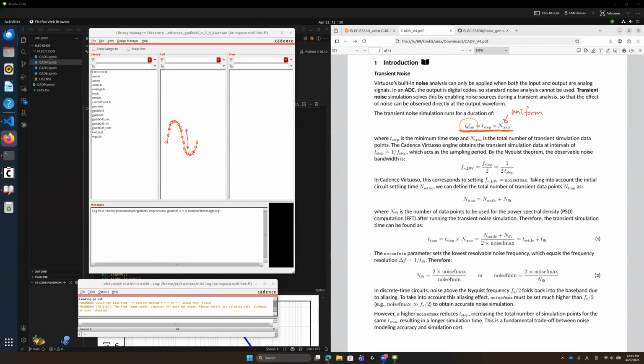According to the sampling theorem, this simulation engine is based on samples. So those are samples, and this is under the theoretical limit of the Nyquist sampling theorem. Let's say the sampling frequency is fs, equal to 1 over f step, the sampling period of our simulation engine. We learned this as the sampling frequency, but since this is a simulation engine, let's call it f step.